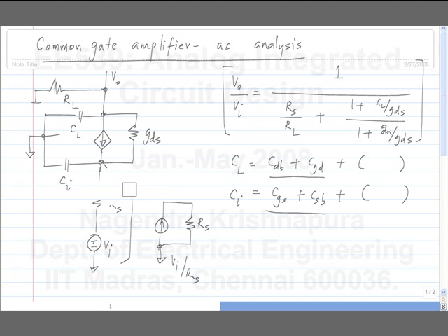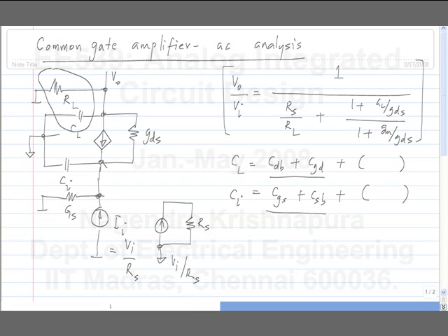That is, I put the current source here. So this is II, which if driven from a voltage source is VI by RS or VI times GS, and there is a conductance of GS from this node to ground. The expression involves GS and GL, and the high frequency equivalent circuit, the only difference is that instead of GL you have the parallel combination GL plus sCL.